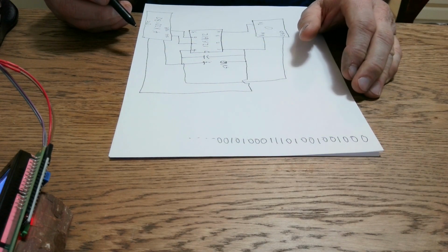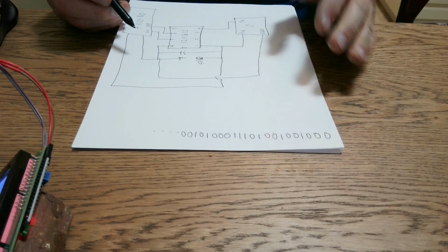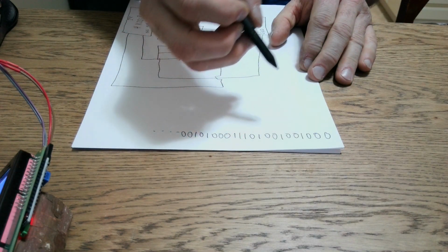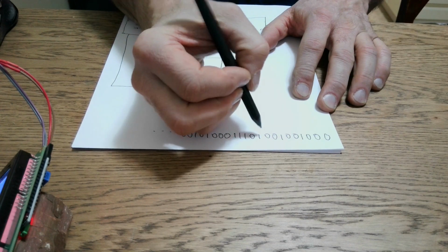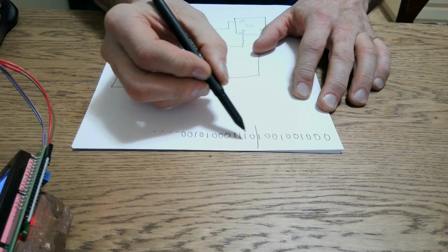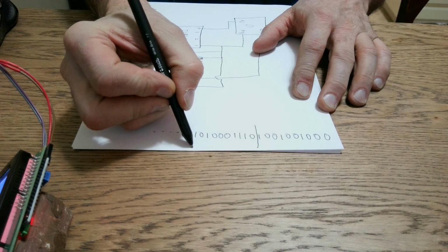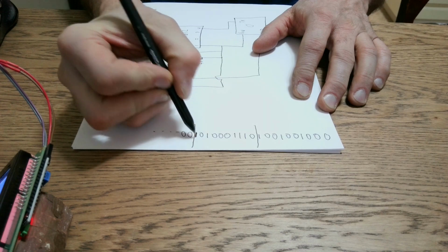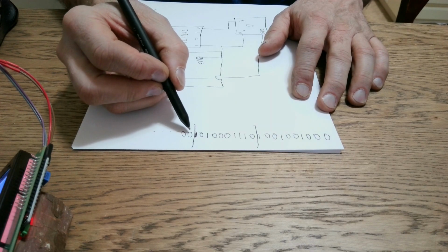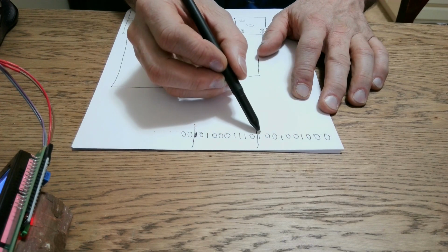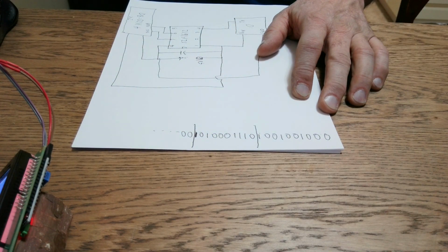So they actually use a 10-bit byte with this because there's a start bit and a stop bit on every single byte. So let me just count out 10 bits here. 1, 2, 3, 4, 5, 6, 7, 8, 9, 10. There's 1 byte, another 10, 1, 2, 3, 4, 5, 6, 7, 8, 9, 10. There's another one. Now I've got 2 bytes that I've just segregated, and you can see obviously there's a 0 to start and a 1 to end on every one of these bytes.